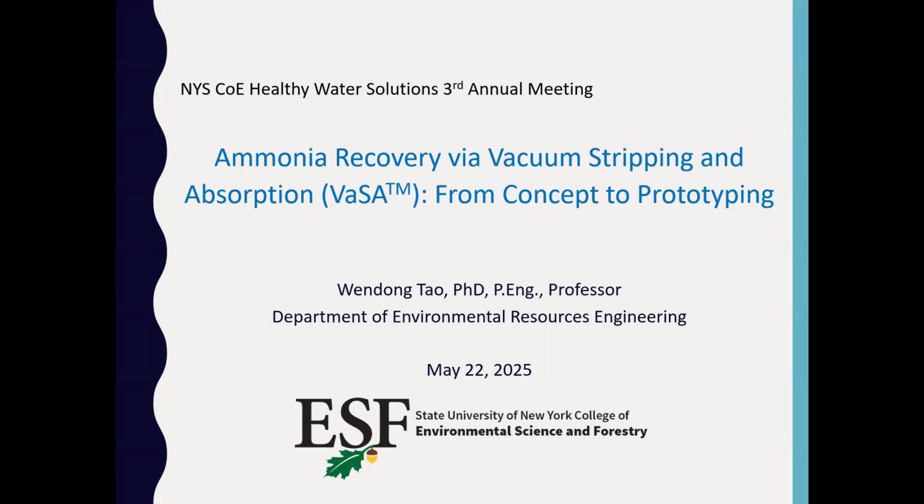Okay, my talk will not be purely technical. It's a combination of technology transfer and research, echoing this morning's plenary session. The technology I'm going to talk about has a very simple principle: apply vacuum to strip ammonia out of wastewater and absorb the ammonia gas into a solution as a value-added product. The principle is simple, but we had challenges when scaling up.